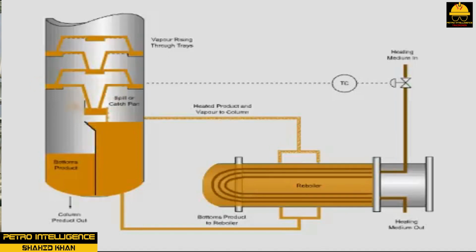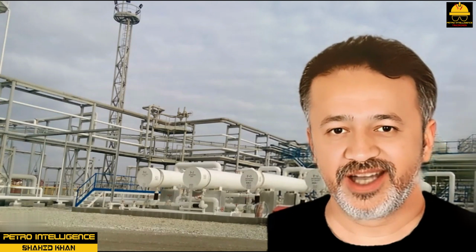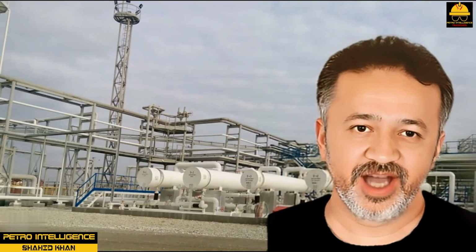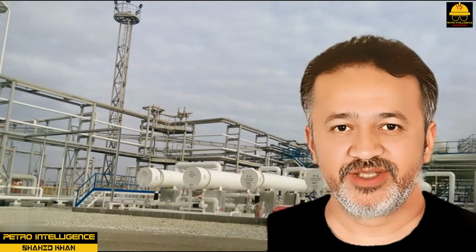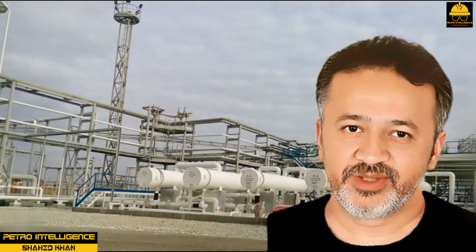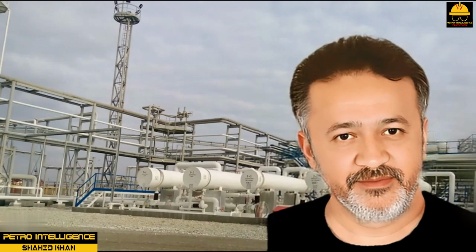A pump is not connected to the column and exchanger unless a forced circulation system is required. This system uses buoyancy forces to flash off and pull in liquid. Newton's third law of motion, which states that for every action there is an equal and opposite reaction, is a basic operating principle of thermosiphon reboilers. As liquids and vapors circulate back to the column, the inlet line provides fresh liquid to support the circulation.